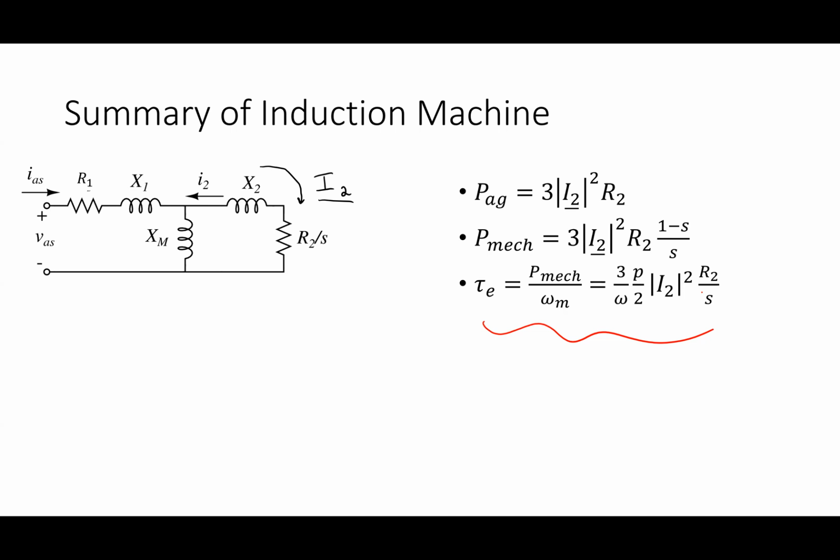Well, its resistance increases as it gets hotter. Yeah. And so that resistance is really sensitive to temperature. If I just start a motor and let it run for a while, I'll see the current kind of decline over time because the resistances are starting to change inside the machine. Even if it's doing nothing, right? It'll just change a little bit over time.